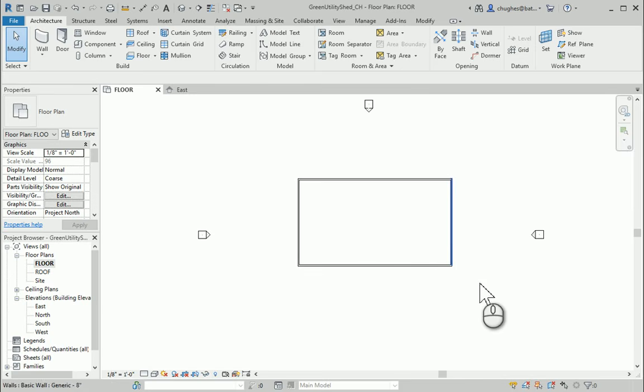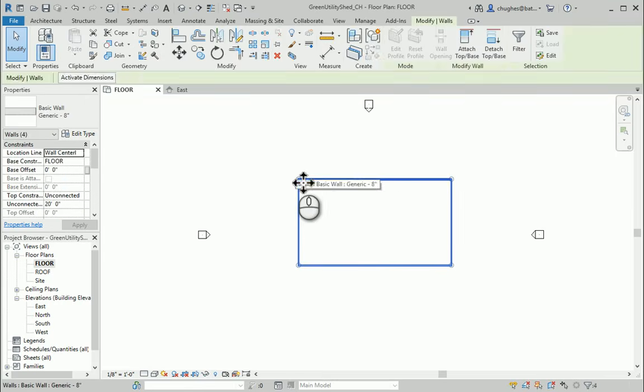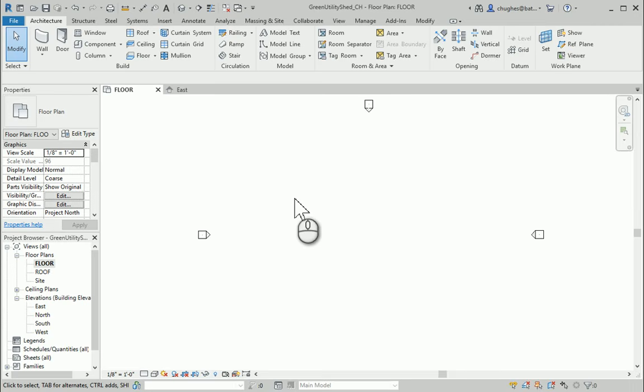Another way that you can select items, I'm going to move my cursor to the bottom right, and then drag, and you'll notice the window looks a little different. It's got these dash lines. This is known as a crossing. So if I just touch an item, it will automatically select the entire thing, whereas previously, I have to get the entire item inside of the box to make the window selection. With a crossing, all I have to do is touch these items. Once I touch, I can hit the delete key, and that will get rid of the walls.